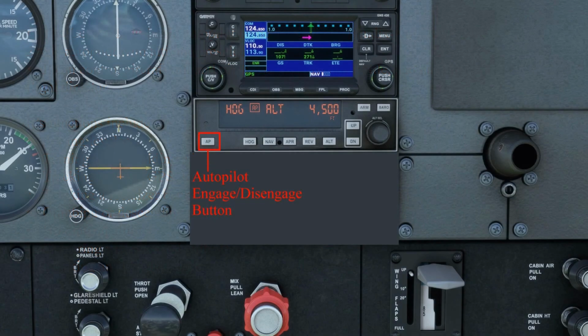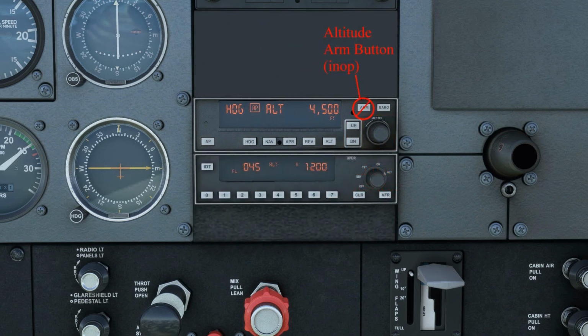Controls on the KAP 140 include an autopilot engage and disengage button, heading mode selector, navigation mode selector, approach mode selector, back course approach mode selector, altitude hold mode select button, vertical trim buttons, altitude pre-select knobs, an altitude arm button that doesn't work in Flight Simulator, and a BARO set button that doesn't work very well in Flight Simulator.